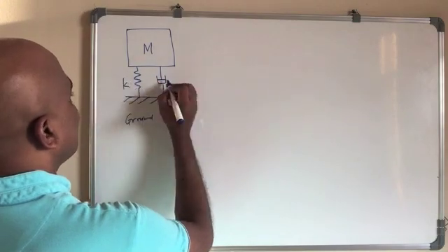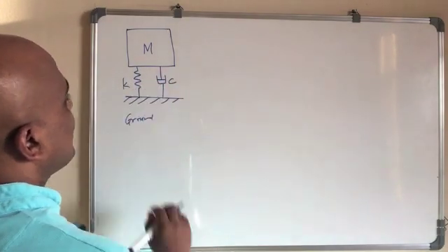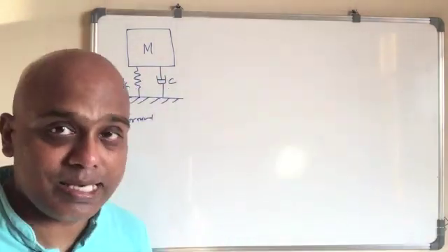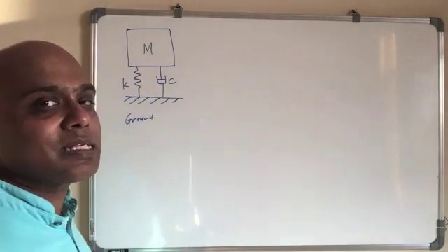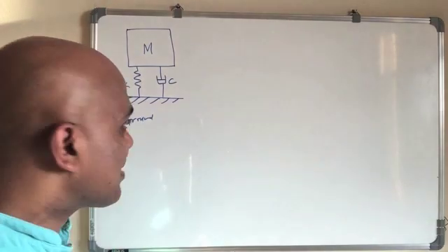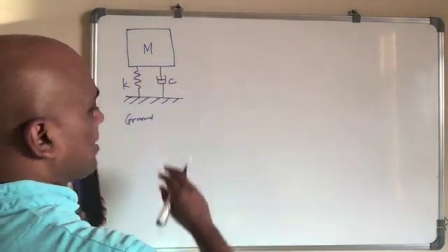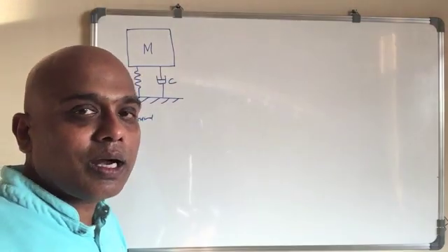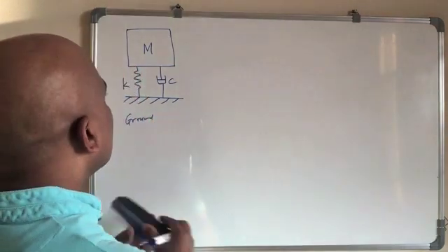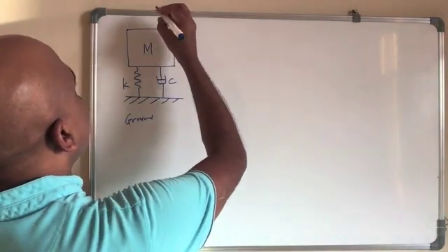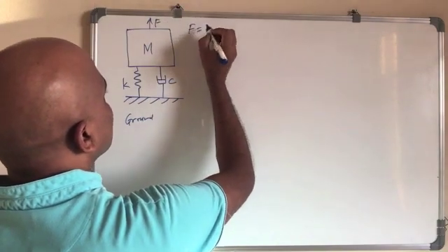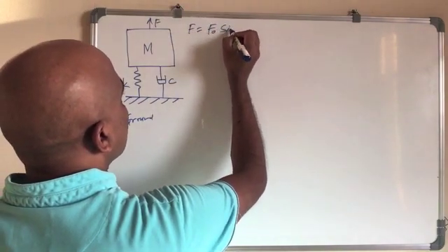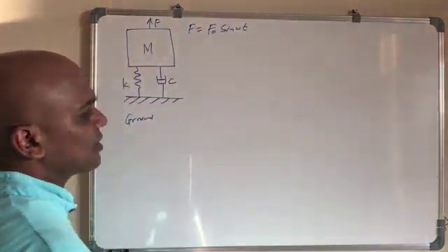Here it is K, we have C here. We have to choose K and C in such a way that the force which is going to be transmitted is less than whatever is a desirable value. So M will have some kind of force, we can say now here, F, where F equals F naught sine omega t.